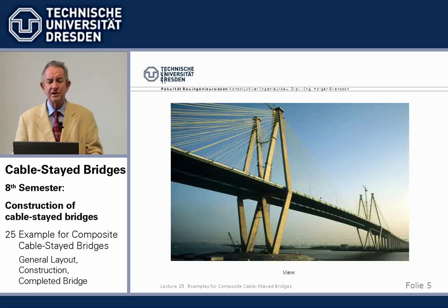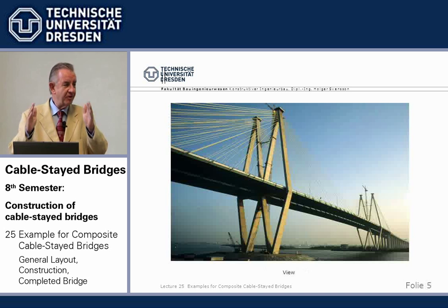So we looked into other cable arrangements and finally settled for 2 separate beams with 2 cable planes each, meaning 4 cable planes. And then it turned out that the transverse steel was only 1/2 of the longitudinal steel required.